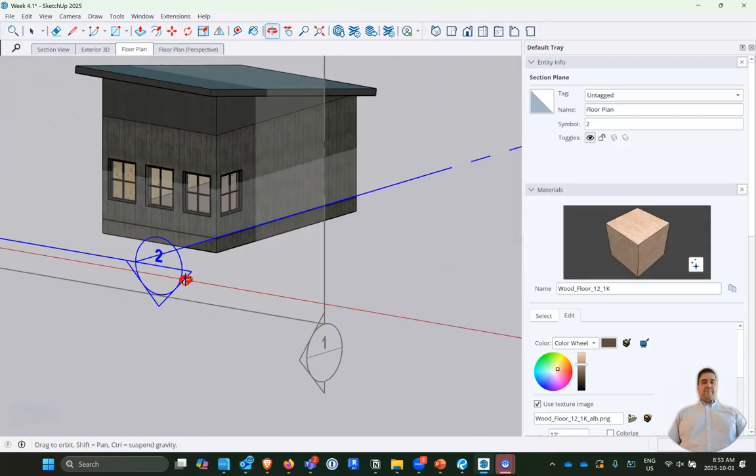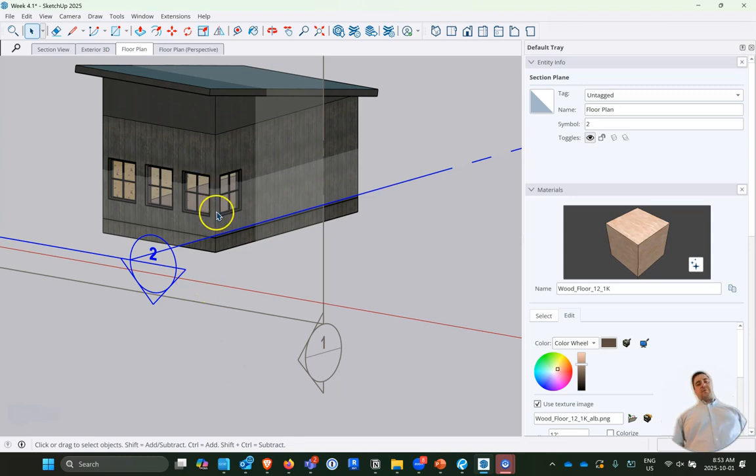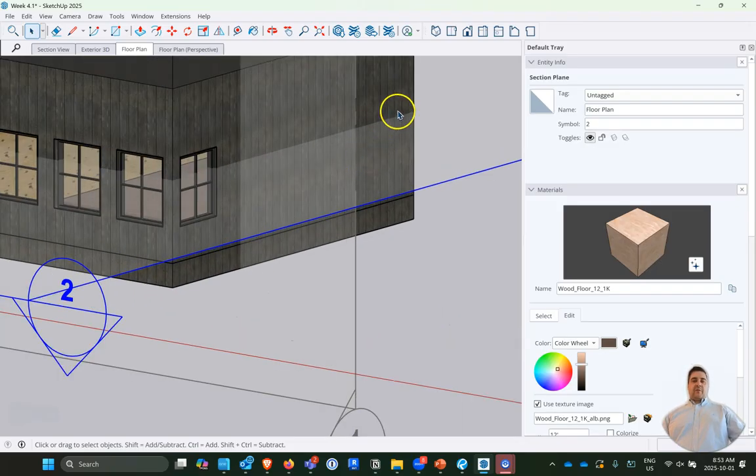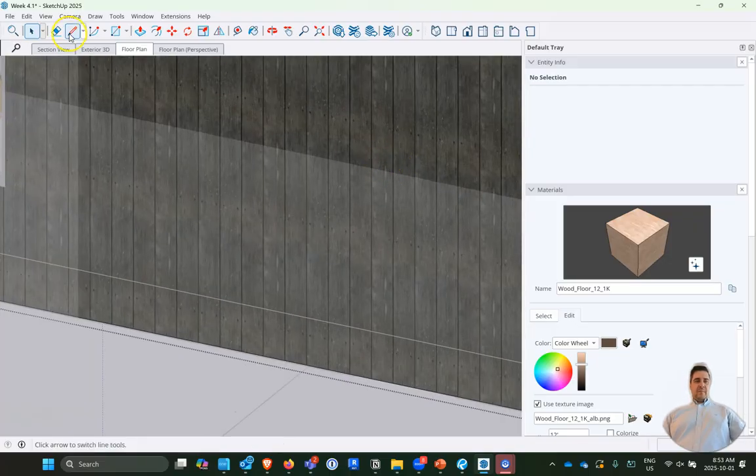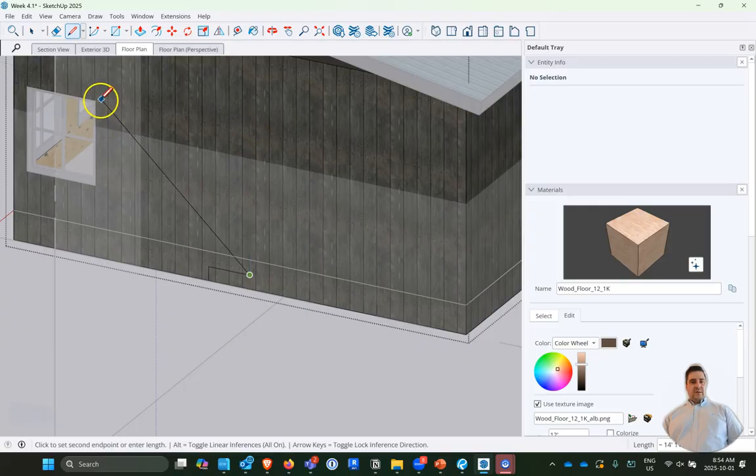So we have our building there. We have windows. Theoretically, we could create a door too. That would be a good thing to do. These windows I made 2 feet off the ground, so if we wanted to do a door, it's obviously the exact same thing. I'll go up 12 inches instead of 24 or 36. So let's go 12, and let's go 36 inches wide. It's a standard door, and then let's see. Did I do this at 8 feet? Oh, that's really tall. All right, let's go up 8 feet for a door.